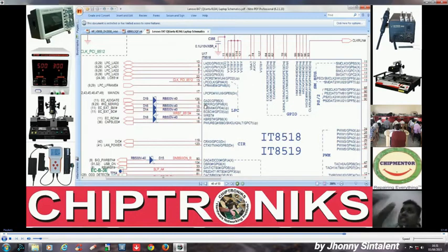How would the processor know? So the IO controller must indicate to the processor that a touchpad has been pressed or a keyboard has been pressed, so that the processor can process this data accordingly, right? So there must be some way to transfer the information to the CPU that yes, a touchpad has been pressed or a keyboard has been pressed, and for that a specific kind of interrupt has been made, and that we call serial IRQ.